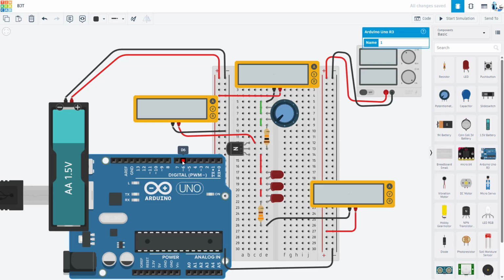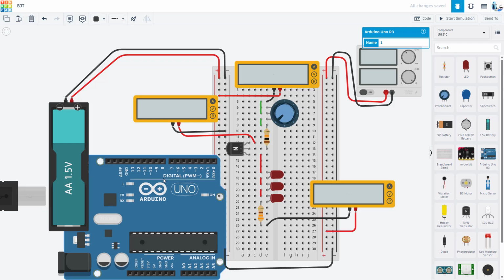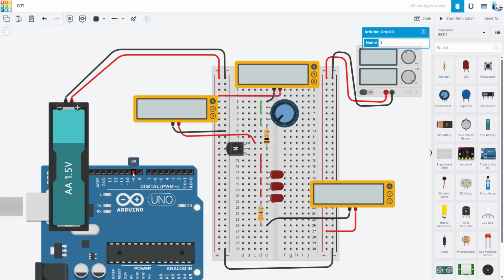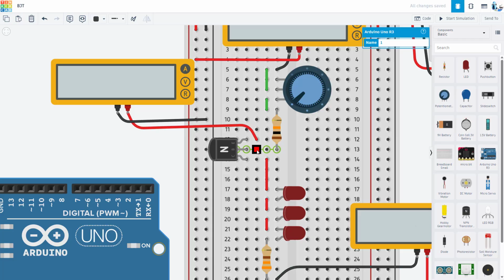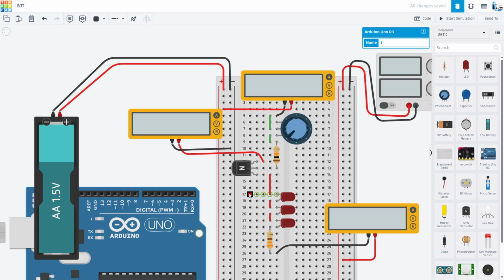Depending on the model of the Arduino, they can provide up to about 20 milliamps, which is enough to drive an LED directly, but not enough to drive a motor directly, or if you need 12 volts because you have a bunch of LEDs in series. The 5 volts from the Arduino is not enough to power that. So the Arduino can provide this lower power, low current control signal into the base of a transistor, to act like that electronic control valve, like a faucet or a hose, that is controlling the larger current, higher power flow through a bigger load.